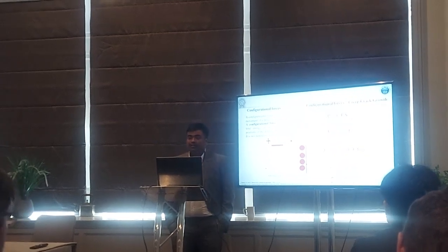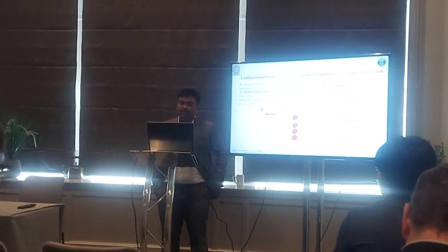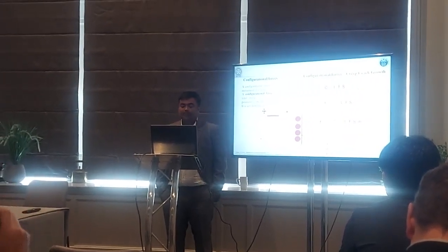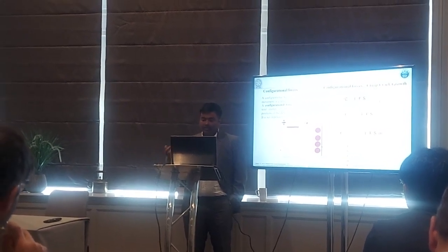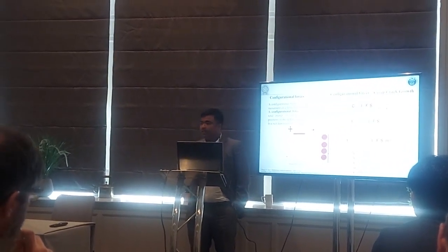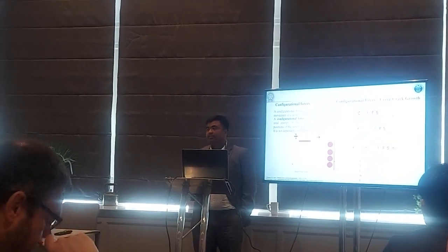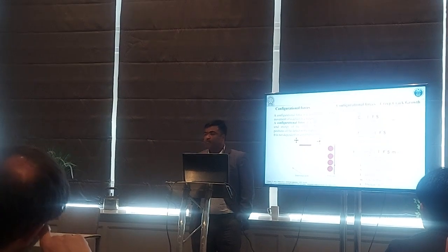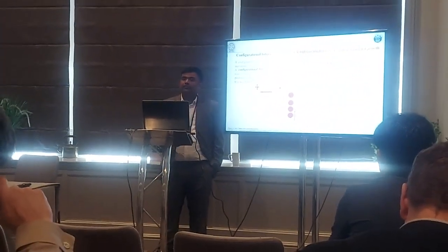The divergence of the tensor converts it into a vector, and the negative sign shows how much energy goes into the system and how much goes out of the system. And suppose there is a singularity at a crack tip, then we can say that the configurational forces are 0 in this condition. So how do we find the configurational forces?